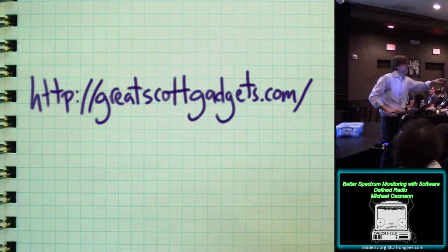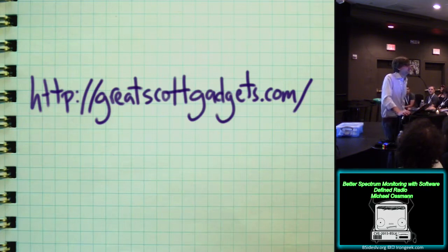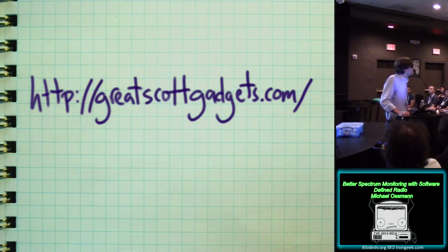We had some really good questions so far. When you eliminate USB as the great limiting factor, what are you running into that's limiting? Yeah, the question is, if we eliminate USB from the tuning time, what is the limiting factor? Why does it take any time at all to tune? And yes, it is primarily the PLL lock time of the frequency synthesizer that is producing the signal.